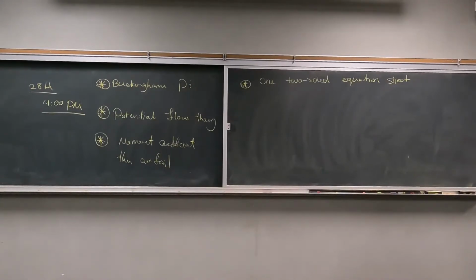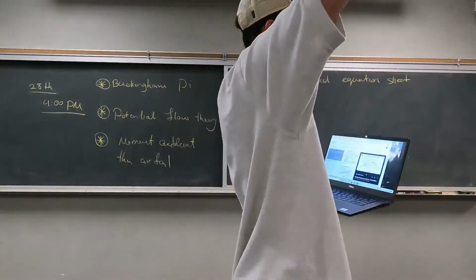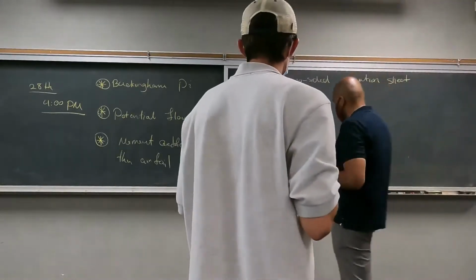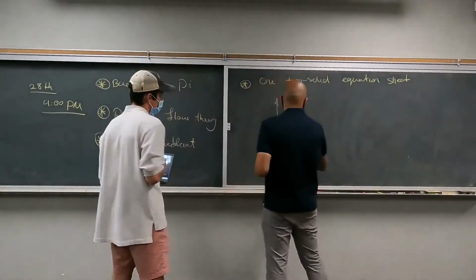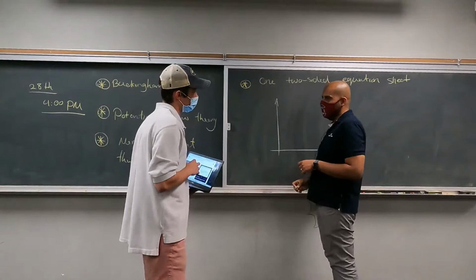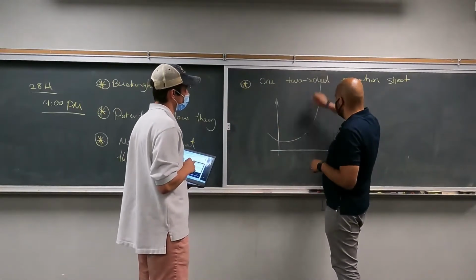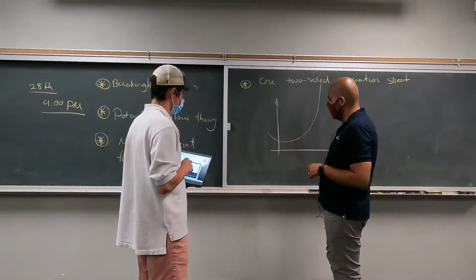It shouldn't look similar if that's what you're asking. For their graph, it has a similar kind of falloff. No, that starts actually low. It should look something like this. They didn't get the stall condition. The idea is during a stall, your drag increases rapidly. So instead of falling off, it goes something like this, exponentially, and it doesn't go to 0 here or negative.